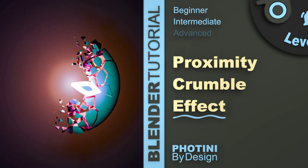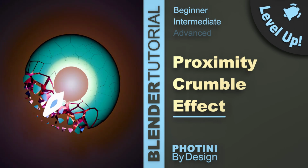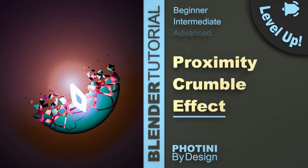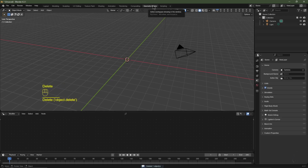Hey folks, in this episode I'm going to show you how to make this crumble effect in Blender using geometry nodes. It should be fairly straightforward to make, it shouldn't take too long, so without further ado, let's get to it. So I'm going to go into my scene, I'm going to delete the default cube, make sure that you're in geometry nodes over here.